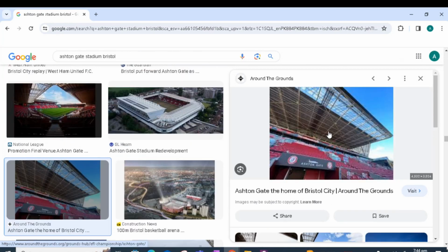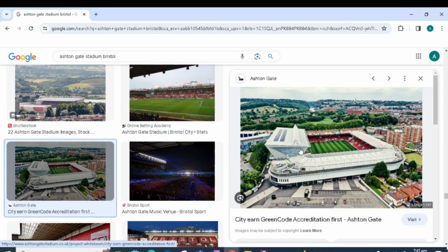This is another view of the roof showing a braced roof, a lattice girder, and these are the cantilever beams being supported by the lattice girder. In this view, we can see the same lattice girder supporting these cantilevers. The cantilevers are hidden under the sheeting. Similarly, there is a series of cantilevers going all around the stadium.